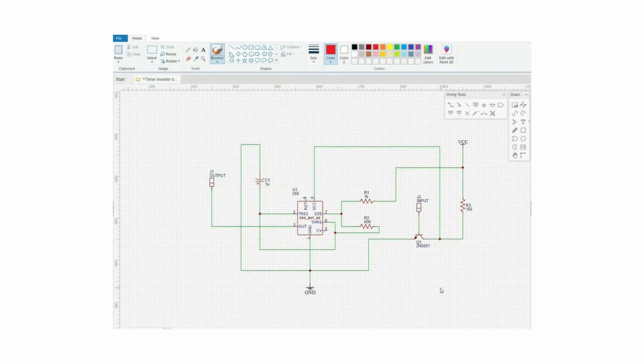a 5-volt circuit. Well, to begin with, output number 7 is high all the time under normal conditions. So output number 7 is feeding about 3 to 5 volts to the transistor gate, making the timer pin number 8, or VCC, go to ground, so the timer is off.